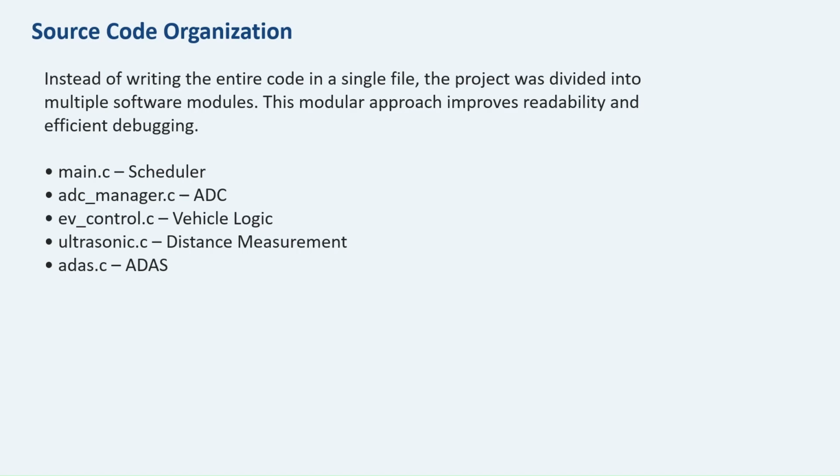And these are the various modules we have used. That is main.c. Main.c acts as the central control program. It initializes all peripherals, GPIO, ADC, UART, timers, all that is used in this internship, and all those are initialized in main.c. Then after initialization, the firmware continuously executes the main loop, and the ADC is used to read all analog inputs from the 4 potentiometers and all that.